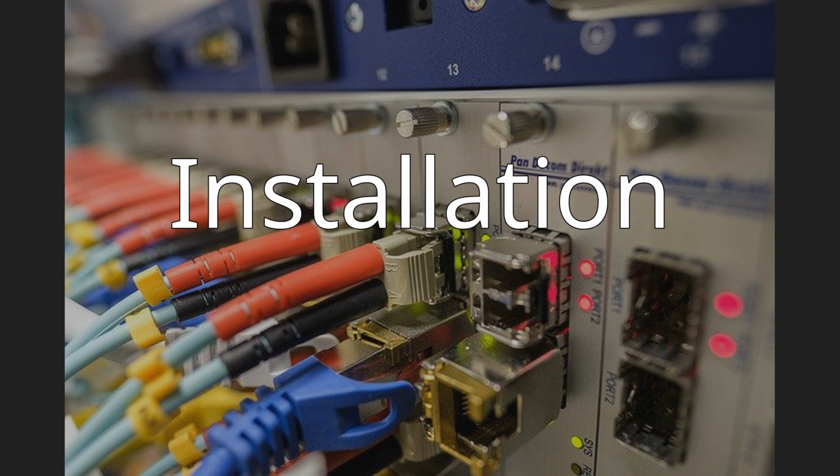Bendable fiber may also be resistant to fiber hacking, in which the signal in a fiber is surreptitiously monitored by bending the fiber and detecting the leakage. Another important feature of cable is its ability to withstand horizontally applied force. It is technically called max tensile strength, defining how much force can be applied to the cable during the installation period.